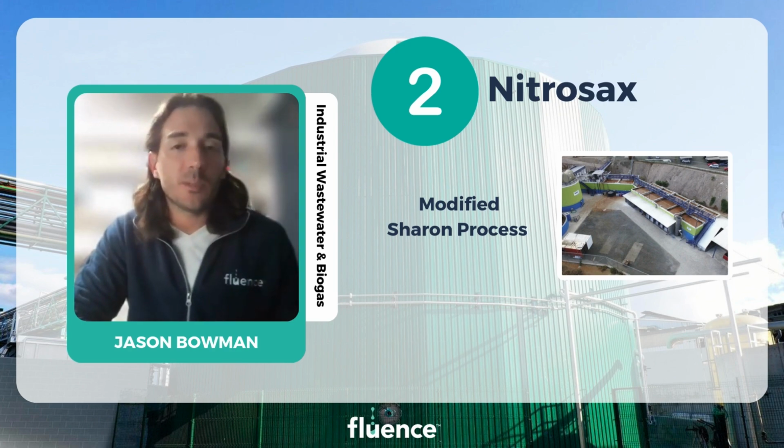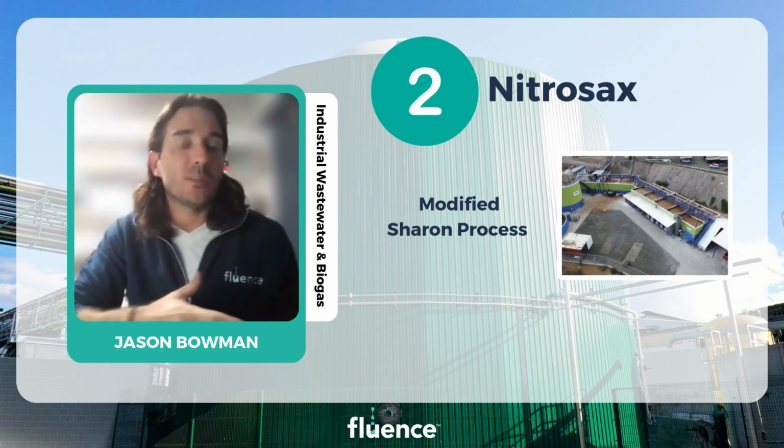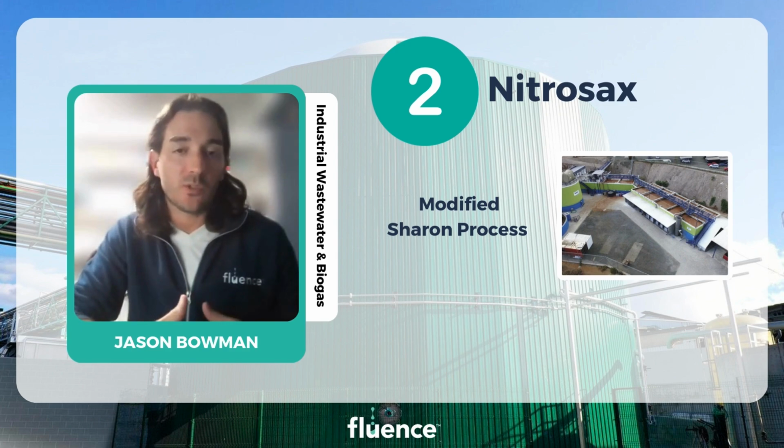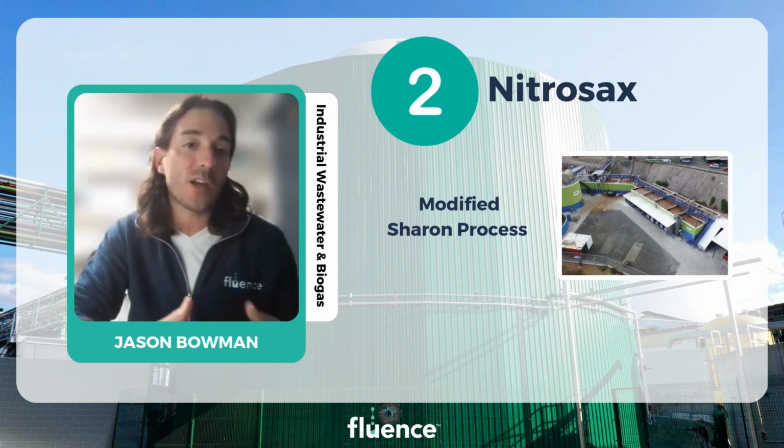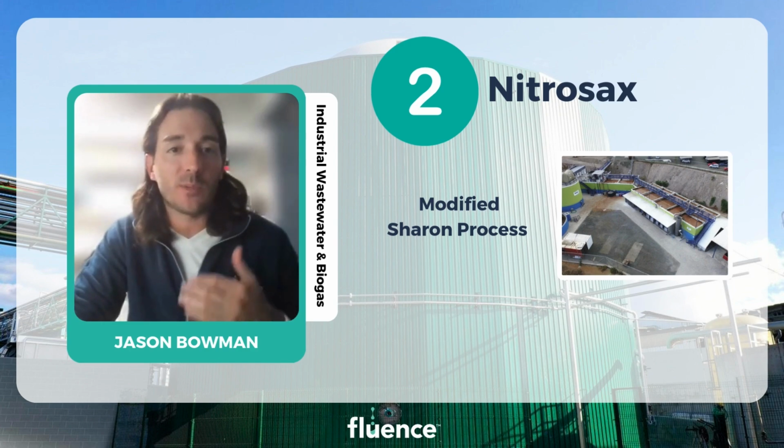So these systems are typically designed as step one in a more complete biological system. And the way these systems are operated is the pH is controlled and the ORP is controlled within a specific range such that we can control the growth rate of ammonia oxidizing bacteria and we can suppress the growth rate of nitrite oxidizing bacteria. So this becomes very powerful because this directly impacts the energy requirements of the system.